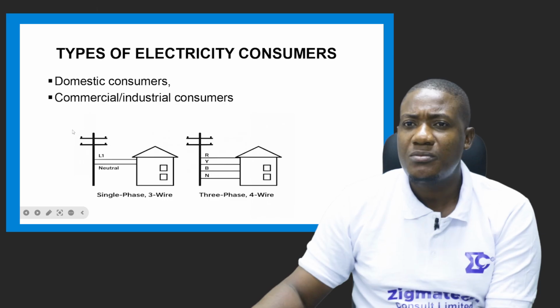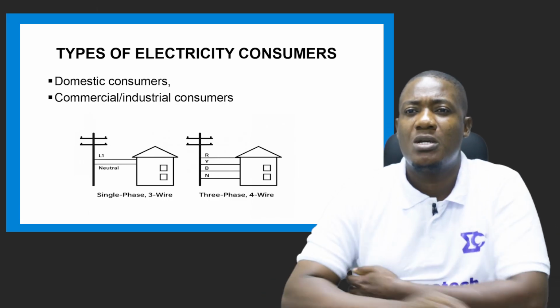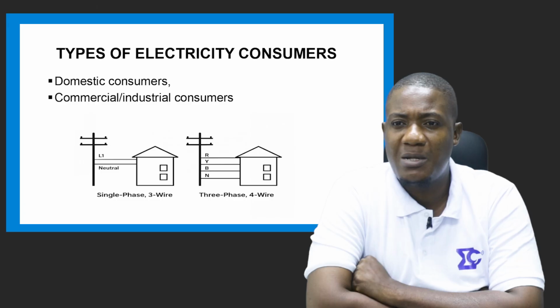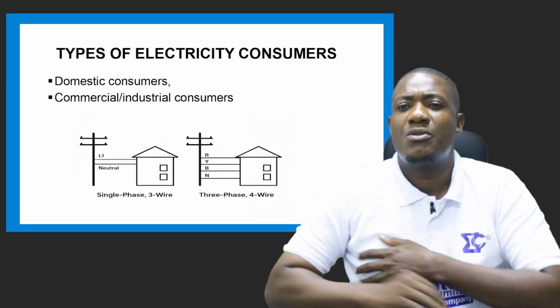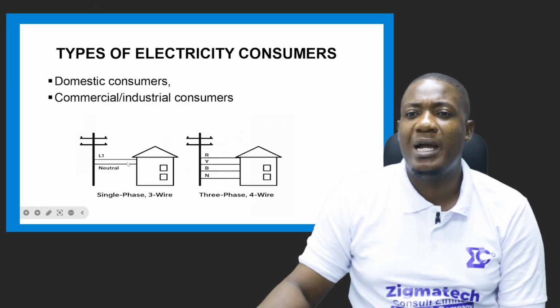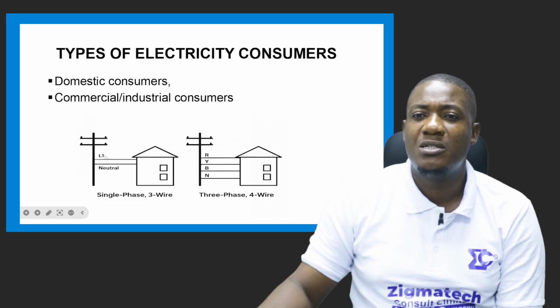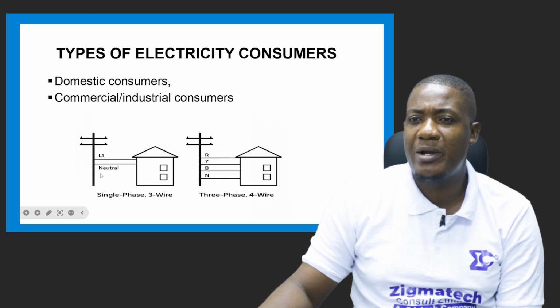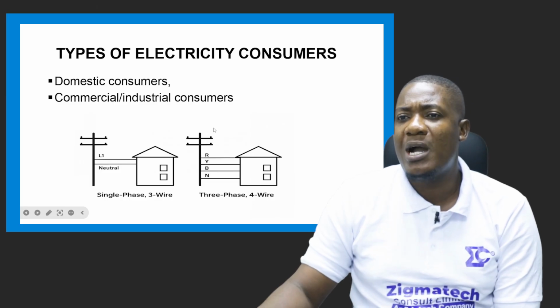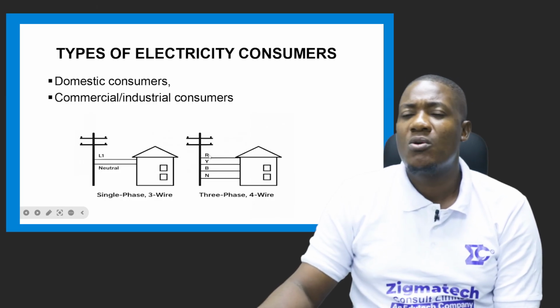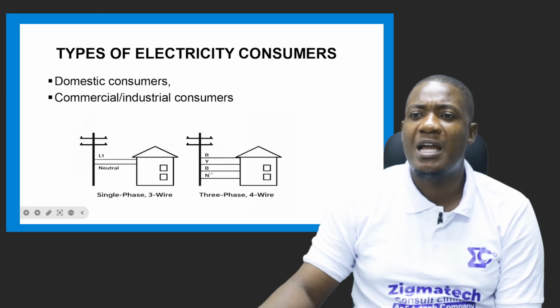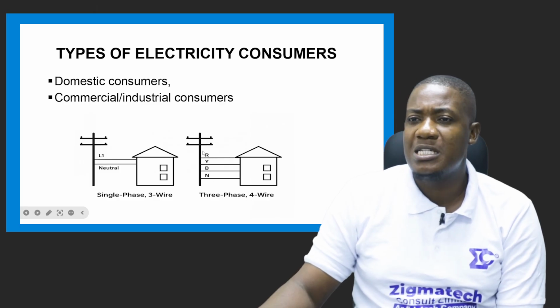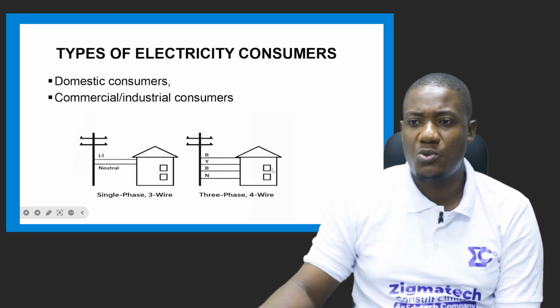Okay. Now, this is a typical example of what I am talking about here, phases. This is a single phase 3 wires. This is the live wire, the neutral wire, and the earth. The earth here is not visible, but we have the earth wire. This is live wire and neutral wire. Then the next is earth. Then we also have from the distribution line, the live, neutral. In this case, this wire is red, yellow, blue, and neutral. Enters your building this way.